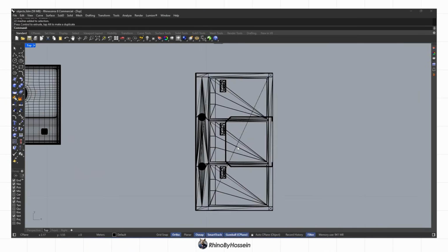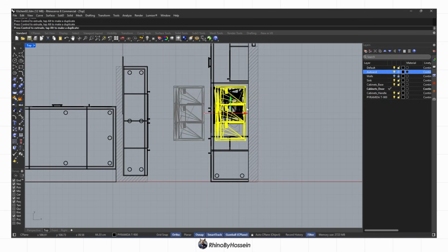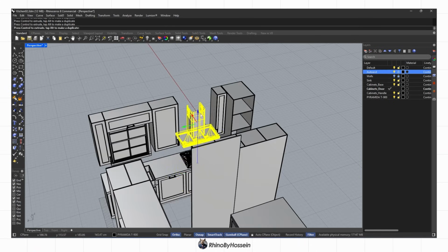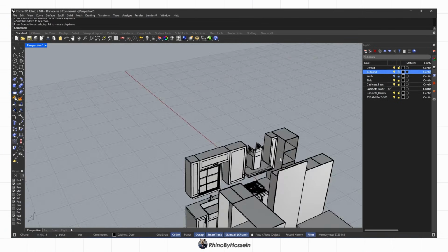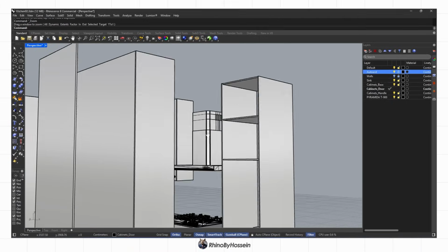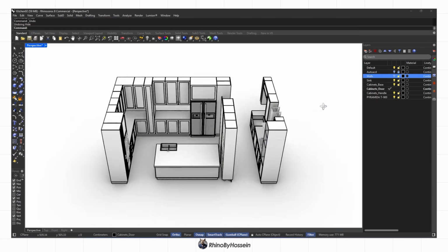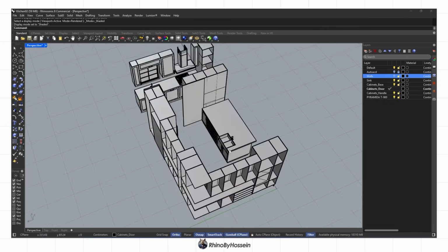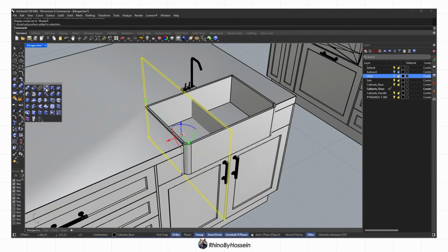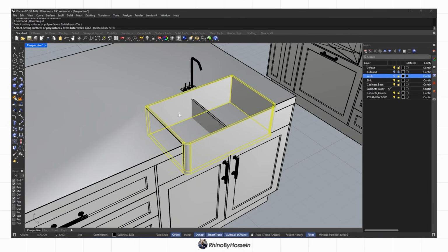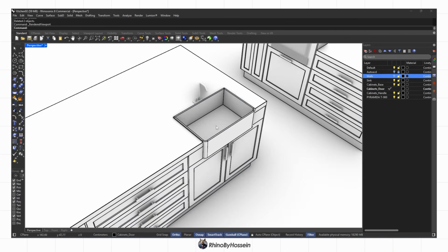Then I place the 3D model of the hood in its correct position, just like the other objects. At this point, almost everything is in place, and only the final touches and cleanup remain. For example, in the clean kitchen sink, one of the vertical members inside the island interferes with the sink. I use Boolean split to separate and remove it, creating a clean and unified interior space.